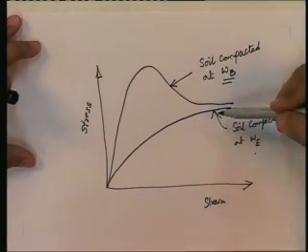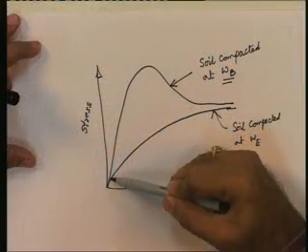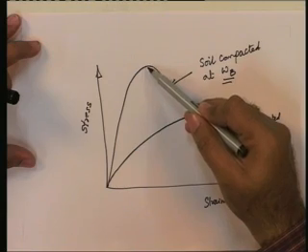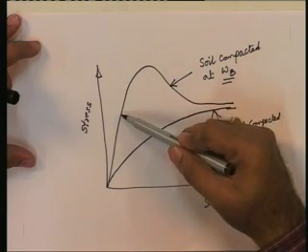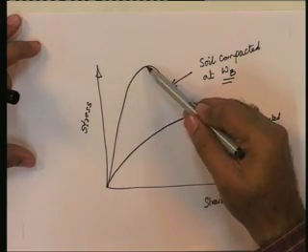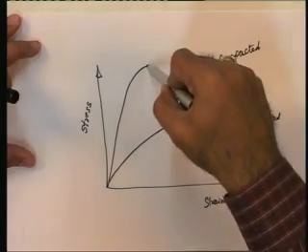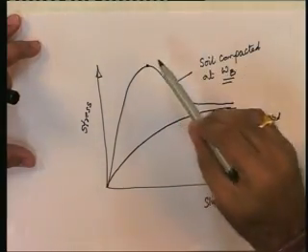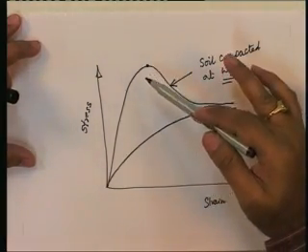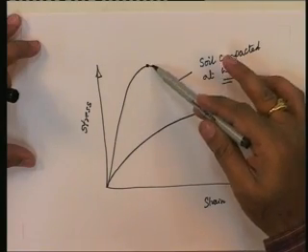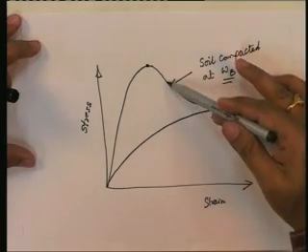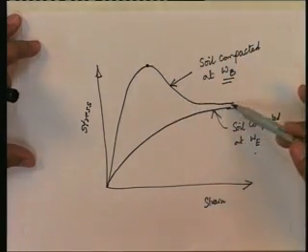Two distinctive behaviors are seen with reference to stress strain behavior for a flocculated structure as well as a dispersed structure. For a flocculated structure, the soil is able to support load, and the modulus is very high initially and it reaches a peak. At this point the truss like connections start collapsing, and slowly the structure transforms again to a dispersed structure.